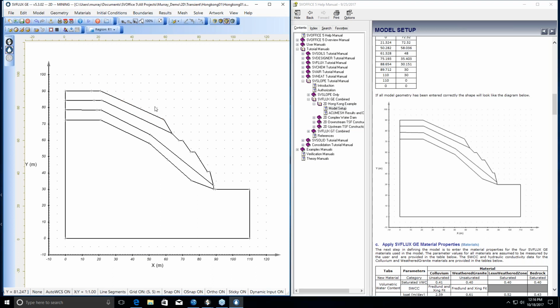Alternatively, what we get people saying is, oh, I entered a point wrong. I want to move the point. How do I move it? Well, you go to point selection, you can select a certain point and translate it or delete it. So there's nice little ways to move geometry around. If you move a point that is on 2 different regions, it'll move both regions if sticky is on. If sticky is not on, then it'll just move one at a time. So there's nice features in the software for moving and editing geometry points.